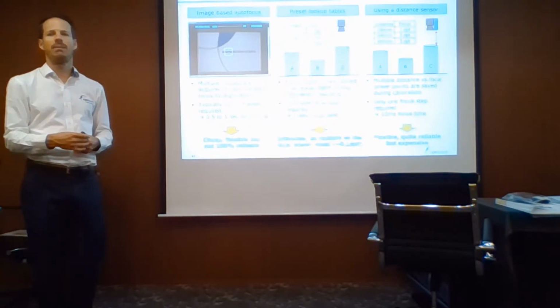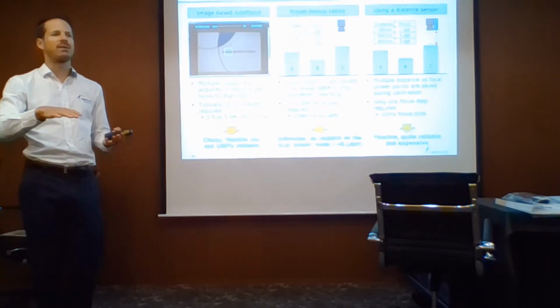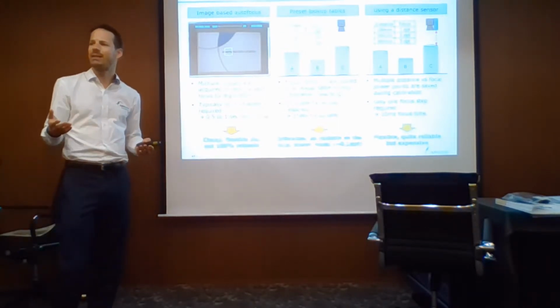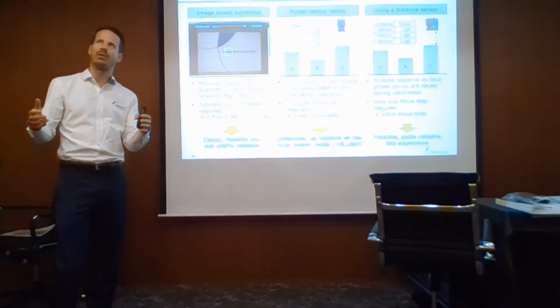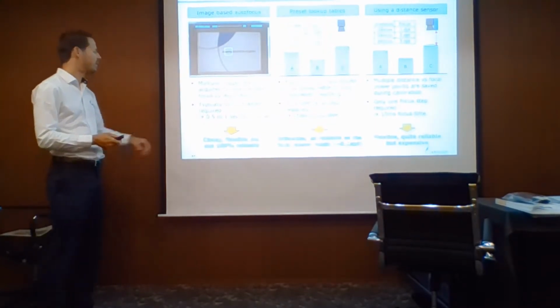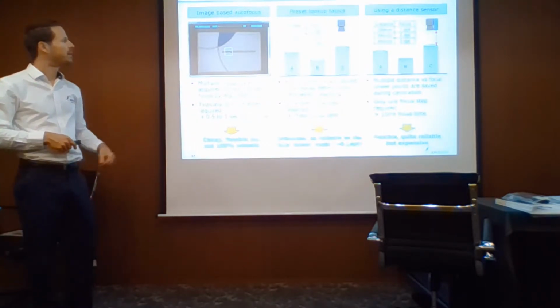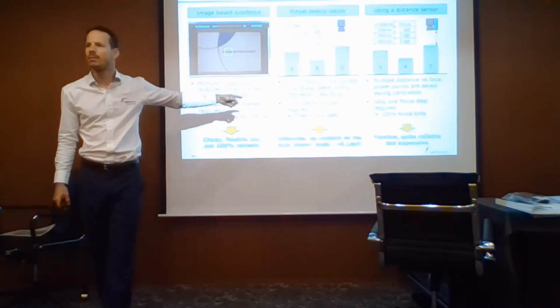So if you do, say, defect detection on a glass, if you do autofocus and you don't find any defect, you're never sure: did I not have any defect, or did I just not find the right focus? So it's only good if you have maybe human feedback to make sure it's correct. What's more common in industry is the preset lookup table.